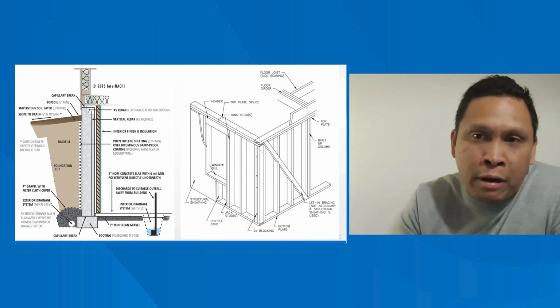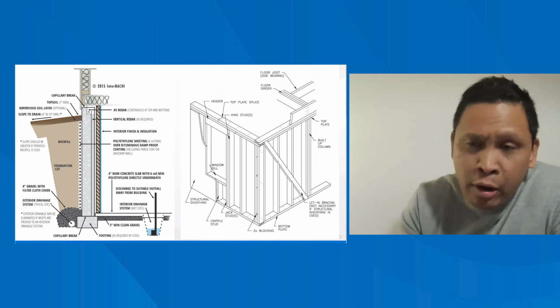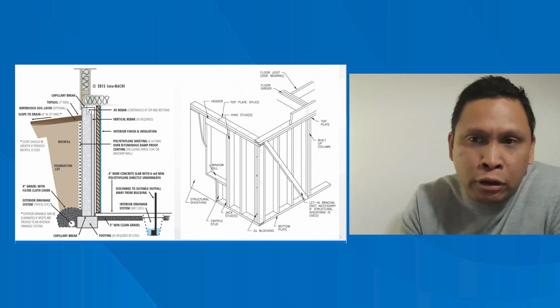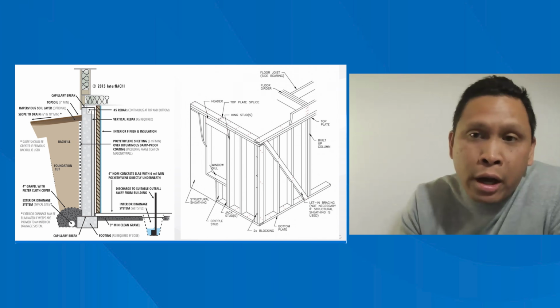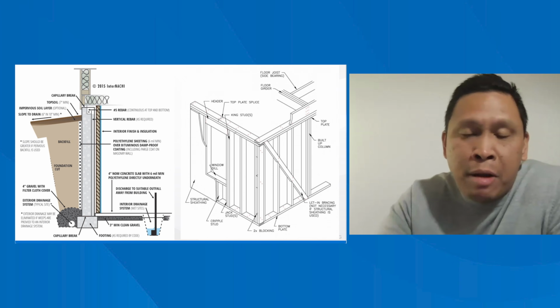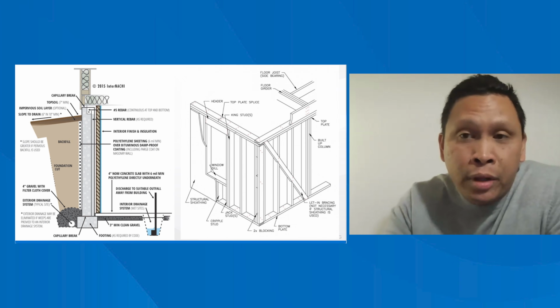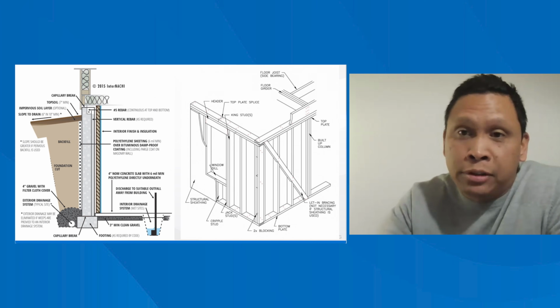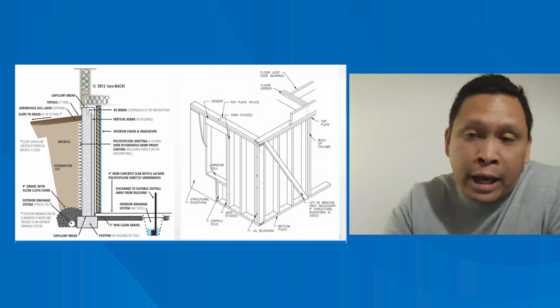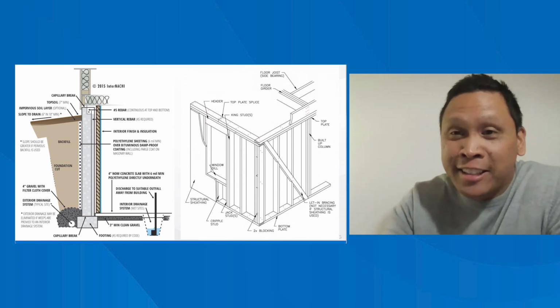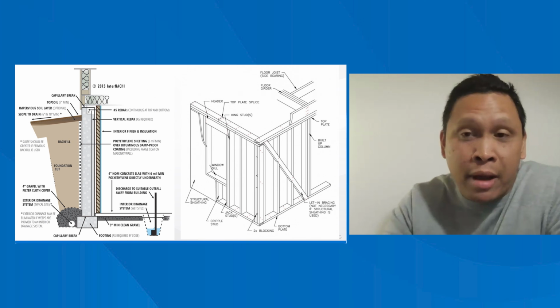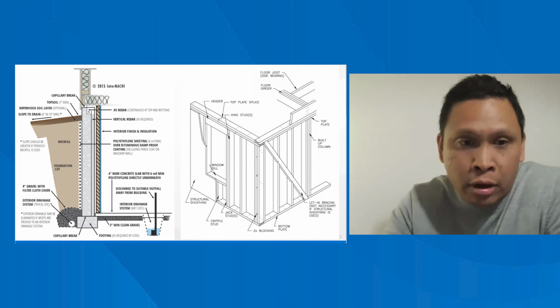I think it is very important to know that if you're on a resale or doing new construction, it's very important to look at as much of that framing system as possible, because who knows, maybe somebody drilled a hole that's just a little too large in that girder. Same thing for a joist, or they notched. I think we've all seen notches in joists that can make the system weaker.